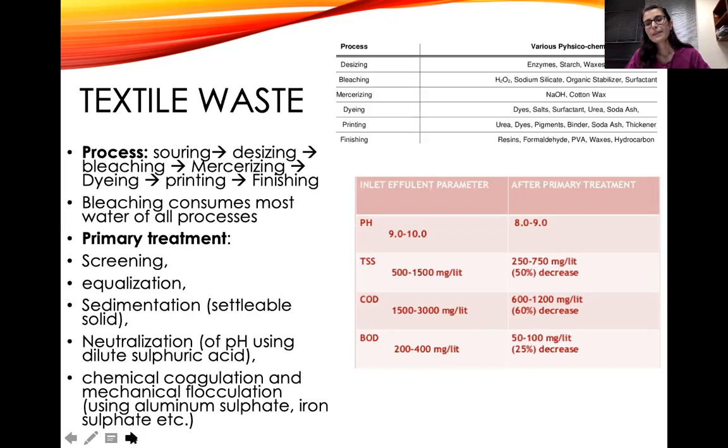And then there is a process called coagulation or flocculation, where the ones that could settle have settled, and the ones that couldn't settle are suspended. So what would you do to this suspended matter? You would either filter it, or you would add a certain kind of chemical that would bring it together and coagulate it or make bigger flocs of it. That's what you do in the next process. So these are primary treatment, because in this you take as much suspended solid and as many chemicals away as you can.